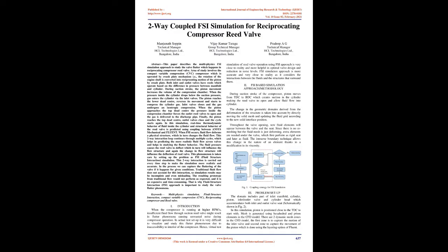Two-way coupled FSI simulation for reciprocating compressor reed valve. Abstract. This paper describes the multiphysics FSI simulation approach to study the valve flutter which happens in reciprocating compressor reed valve. Area of study involves the compact variable compression, CVC, compressor which is operated by swash plate mechanism, i.e., the rotation of the engine shaft is converted into reciprocating motion of the piston by swash plate.